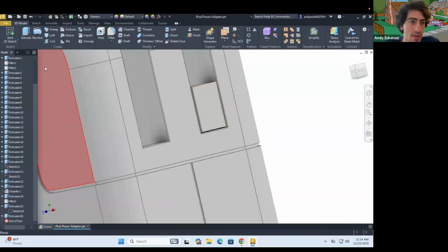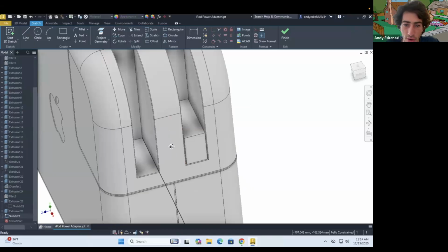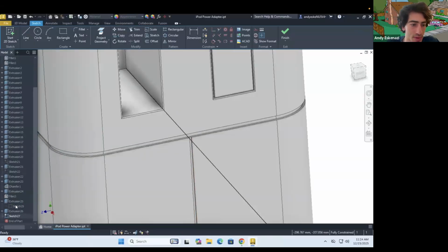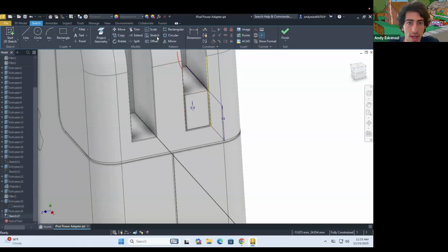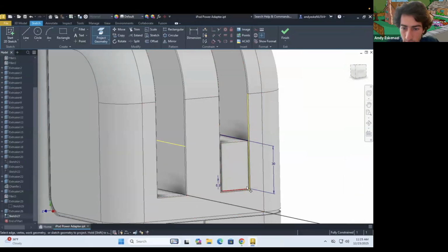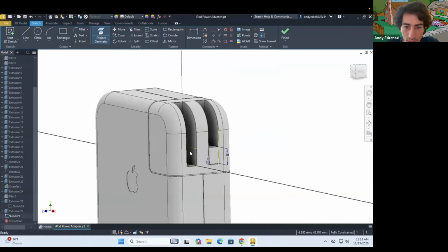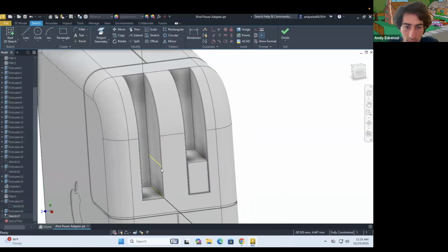Now we do the exact same thing. So we go here to sketch, sketch onto that face. Again, a lot of repetition, I know, but it's the key to doing these things properly. I can show that sketch. That way I can go here to Project geometry. So I'm gonna project, say, the bottom line. That's as much as I need. In fact, I can go back to that sketch and change the visibility.